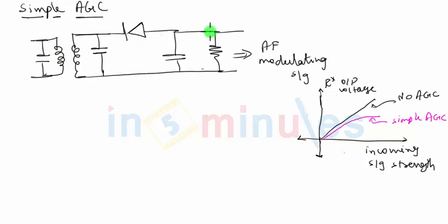Now whenever such is the case, if I draw the final output waveform, I will get the negative envelope of the modulating signal, and not just that, this negative envelope will be shifted by some amount which will be the negative DC signal. Now if you remember, we had taken one extra path from the output of this circuit.